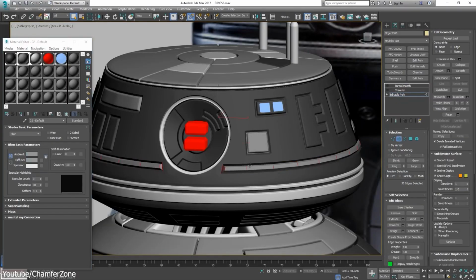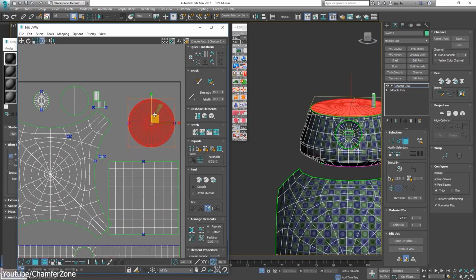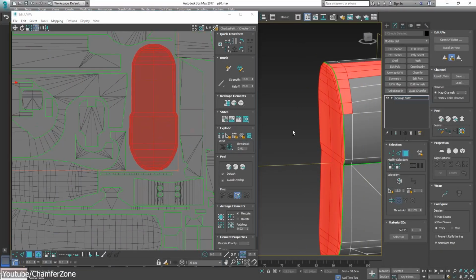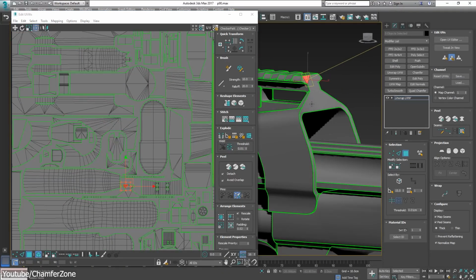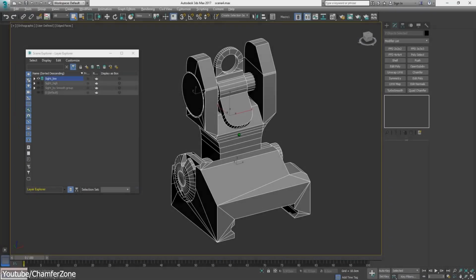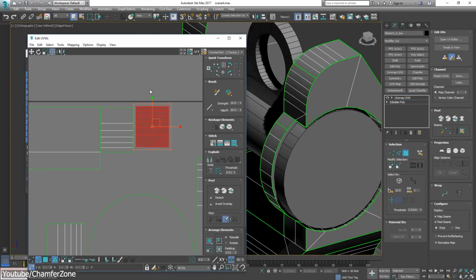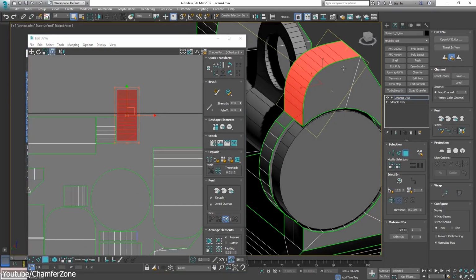After finishing the modeling process and before starting the texturing process, a mandatory step is to generate UV maps. Textures are 2D images, and we need a map to project these flat images onto 3D models. The general process of creating these maps is called UV unwrapping, and it is a purely technical and tedious process that is generally disliked by the majority of artists.